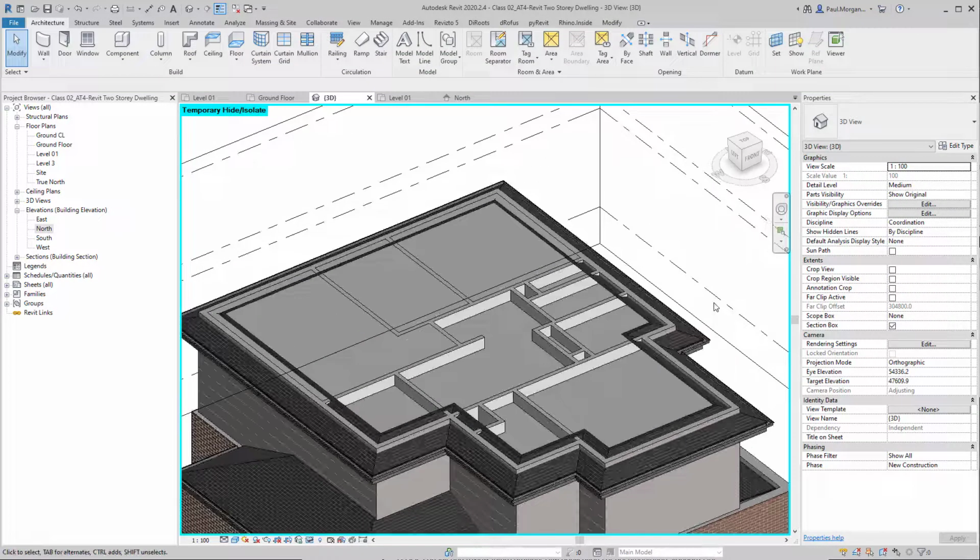So there's no right or wrong here. Generally, I would always say you stick with the relative floor level and offset from there, because basically everything in construction is measured from the floor level upwards, not from the ceiling level downwards. But again, in this project, maybe do one way and one the other. Trial referencing a floor level on the ground floor, and then try referencing the ceiling level on the first floor.